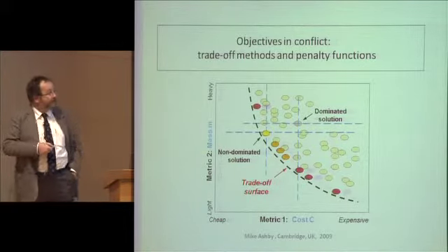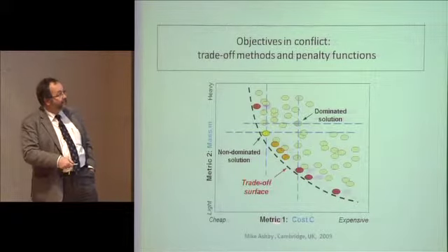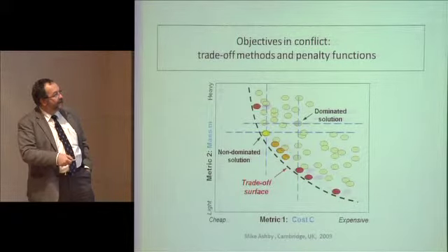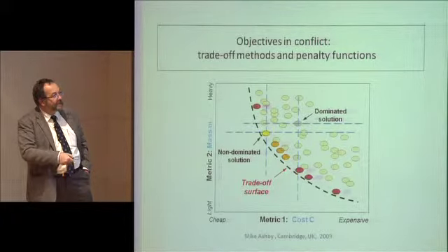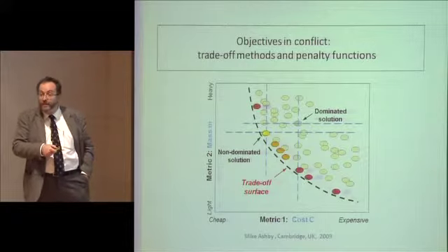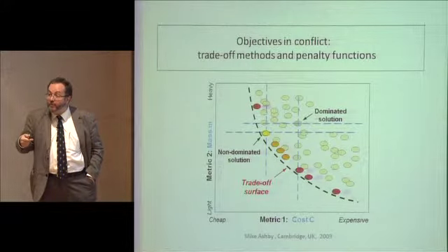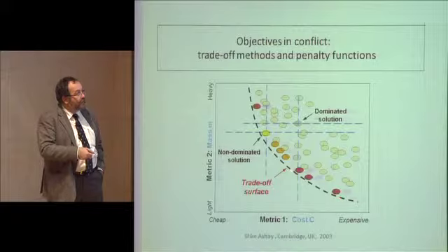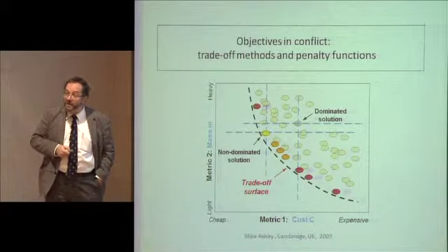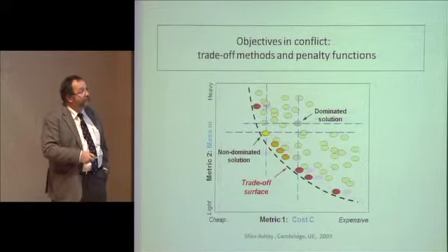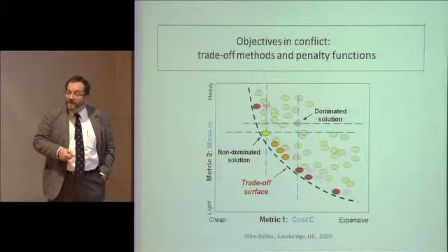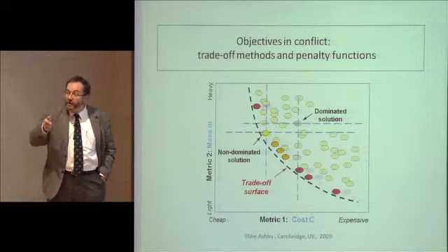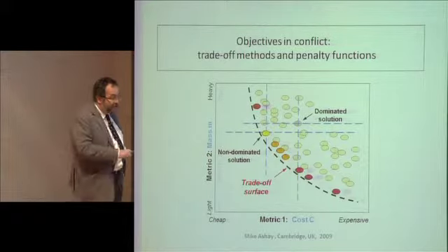When you have contrasting objectives, things are a bit more complex. You have the mass performance, you have the cost performance, and you have the Pareto front, with solutions that are not overwhelmed by any other solution. So in order to select between those, of course you can, because if you're not on Pareto's front, you're sure that it's not going to be an optimal solution. So they are all optimal solutions, and therefore you need to assess the trade-off between your two objectives.